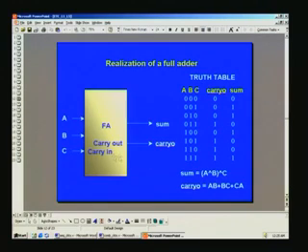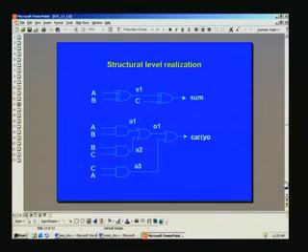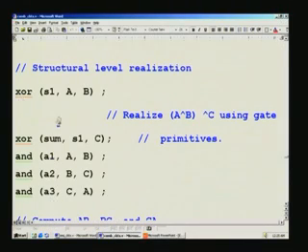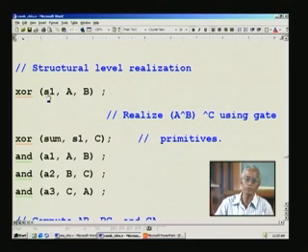So, for the full adder, I do not have to say the sum, carry, truth table, and this is the final thing. Here, in order to implement using gate primitives, whatever you see as the circuit, you can straight away implement. This also has been explained earlier. So, that is what we are doing here. And note that this is an output and these 2 are inputs for an exclusive OR. And if you want, you can say U1, which will instantiate, and there is no need for you to put separately here. Probably you can put a comma and add one more, U2, like that.